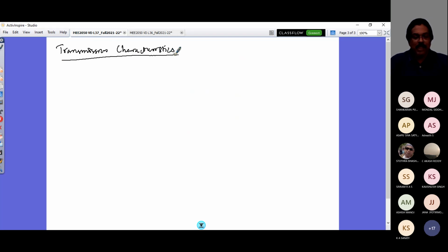So when I look at transmission characteristics, you can have many types of transmission. We always like to have a manual gear transmission system. In our vehicle, we have a manual gear transmission system. And you see nowadays that the transmission system also has got its advancement. We have an automatic transmission system with an application of torque converter, and we have continuously variable transmission system. We also have hydrostatic transmission system in heavy vehicles and so on.